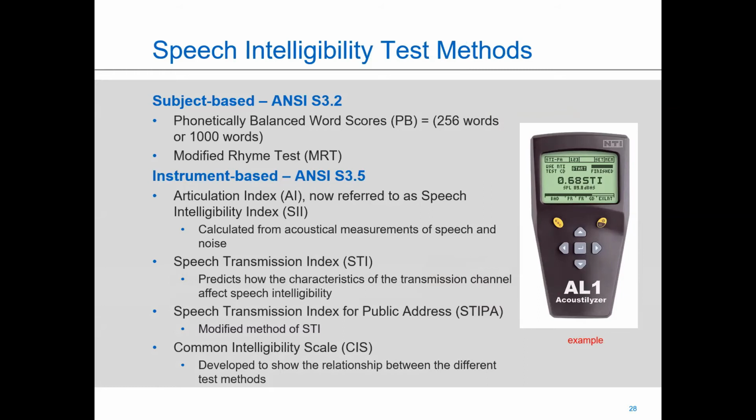It's basically, I think it's a slide in here. Intelligibility is more speakers. That's the bottom line. Lower taps and more speakers. If you got a room that you'd normally be putting one in, if it needs to be designed for intelligibility, you're going to be putting 4 to 5 in, and the taps are going to be much lower.